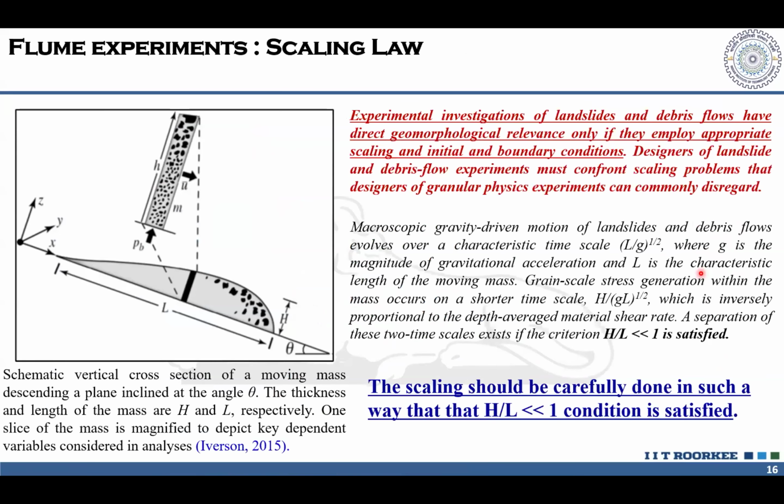What we have to do is to test whether the rainfall-induced landslide hypothesis, or the theory that is applicable for soil landslides, will be applicable for landslides where you also have larger material or not. Traditional or practicing engineers will be aware of more than what we do. But what we have tried to understand from here is the behavior, whether during the rainfall, the movement from the groundwater level from the negative regime to the positive regime will hold true or not.